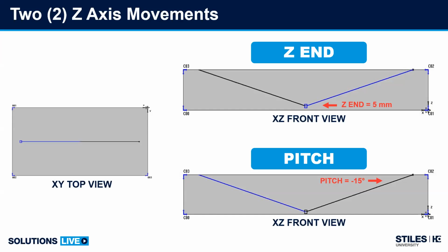Again, we'll get into some tooling specifics, but if you look at the second illustration, this is pitch. Produces almost the exact same design, a little bit different in my Z endpoint, but this is a -15-degree angle. Okay, I know that value. So again, when I design in the 3-dimension, I use the Z commands, I definitely use the view and I look at the front of the panel. I need to see where that line is ending in Z for machine safety for the tooling.